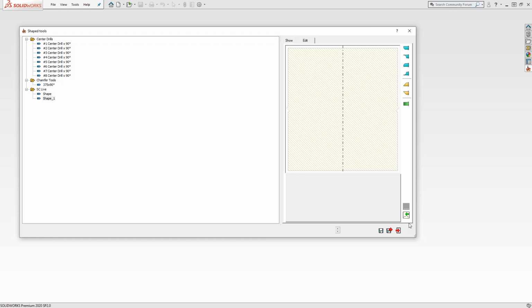100%, and that's actually the procedure that's listed in our shape tool video on the YouTube channel, either yours or mine. I forget which one we show it on, but that's exactly the procedure we take. Because oftentimes, like Kevin said, your supplier will supply you with a STEP file or an IGES file, or sometimes even an STL file, and you'll just take that cross-sectional sketch, paste it into the same window, so you don't actually have to build the sketch yourself. It's an additional step, but you're getting that complex shape.